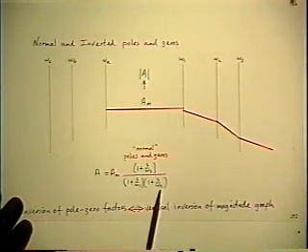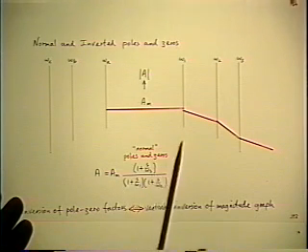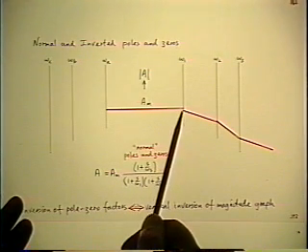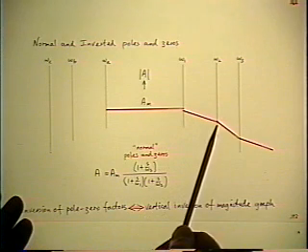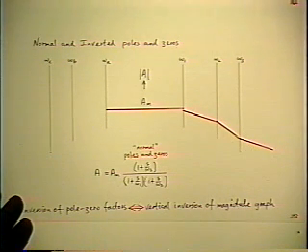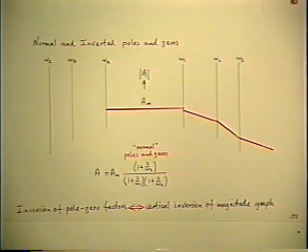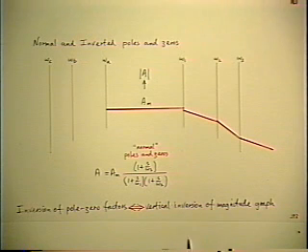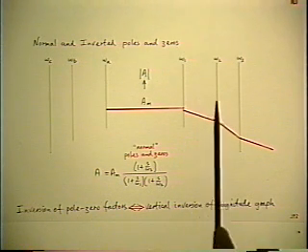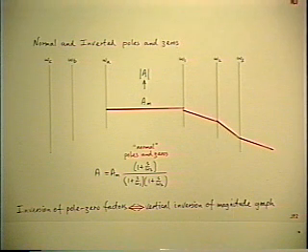The omega 1 and omega 2 terms now are in the denominator, corresponding to poles at omega 1 and omega 2, and the omega 3 is now a zero in the numerator. So this is simply re-emphasizing the fact that poles and zeros are interchangeable, corresponding to a vertical inversion of the asymptote graph.